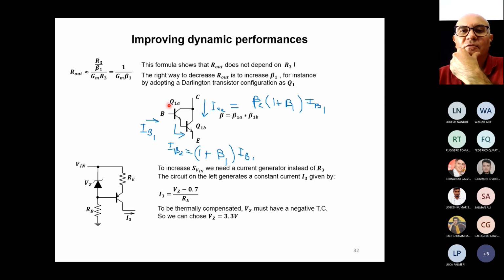So with this Darlington connection, you have what they call a super transistor or Darlington transistor, whose beta is the product of the betas of the two transistors. I don't say exactly it is beta squared, because usually the first transistor is a small signal transistor, the second one is a power transistor. For small signal transistors, the beta is in the order of 150. For power transistors it is in the order of 50. So you have to take the product of the two. Typical betas for a Darlington are something between 1,000 and 10,000. So it can be very high.